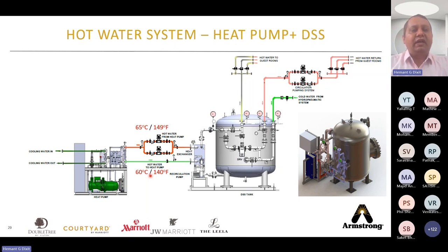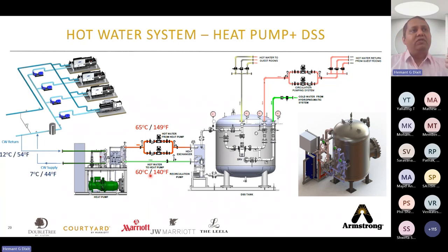In the hotel industry, the majority of steam application is either in laundry or for bathing. And bathing always requires 60 degree water, just to keep the global guidelines intact. ASHRAE and others always talk about maintaining 60 degrees in the tank to kill Legionella. Heat pump is the right application. With a heat pump, even 65 degrees, you can easily maintain a constant 60 degrees in the mixing tank. With proper application like a DSS, you can still maintain ASHRAE 188 standards. Many hotels like Marriott, Hilton and Leela got this benefit. So these are the different applications for different industry segments.